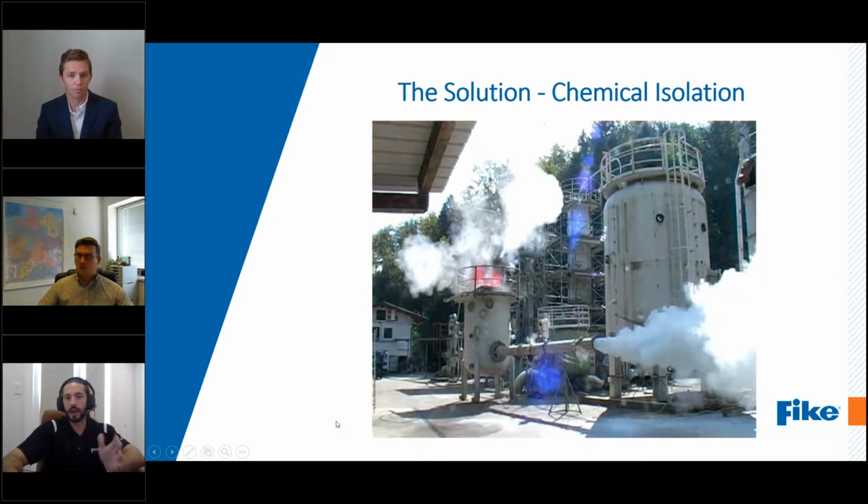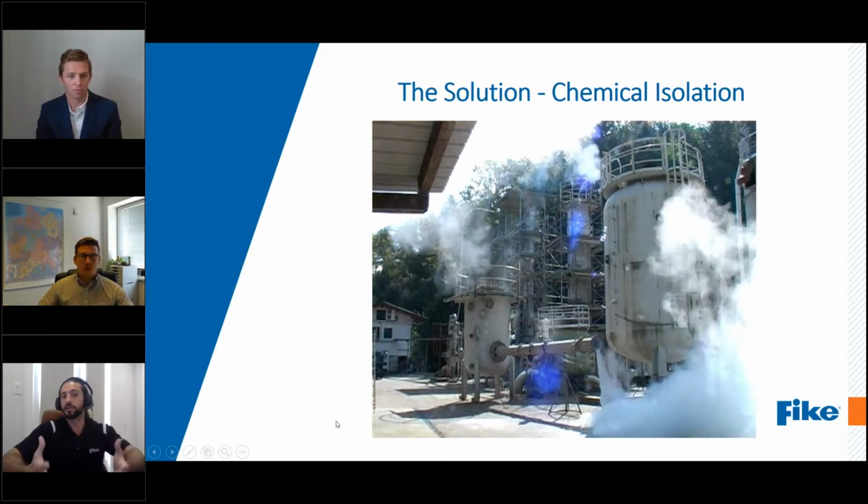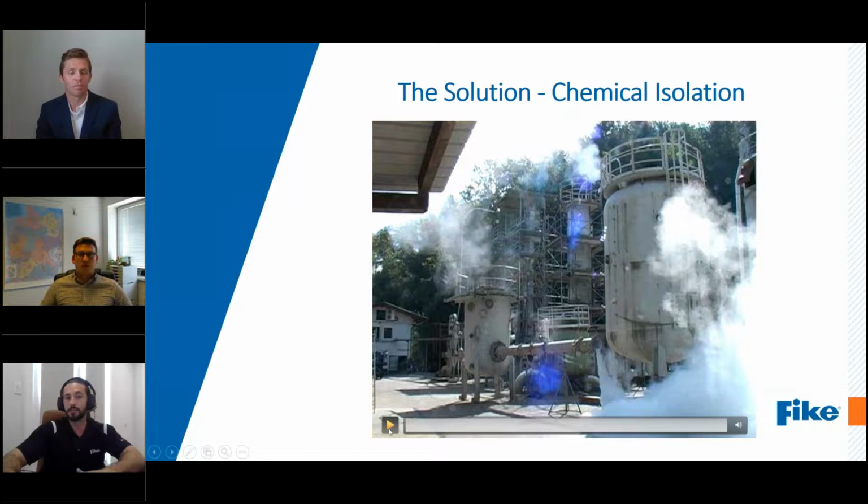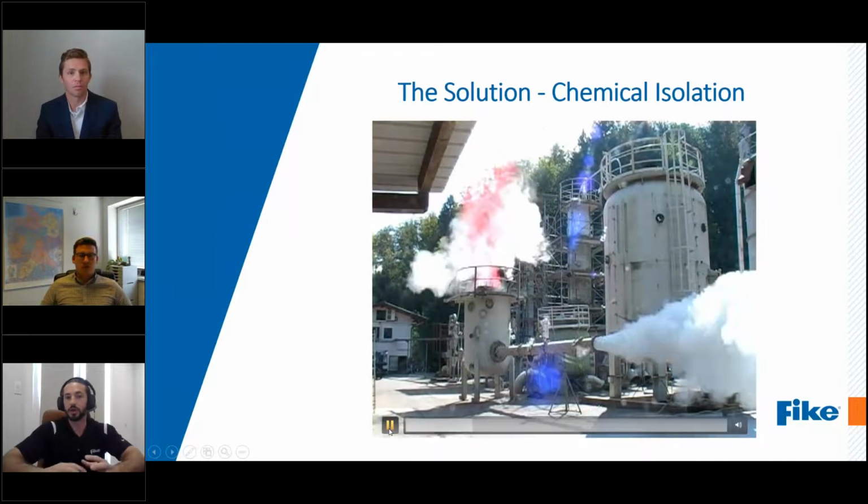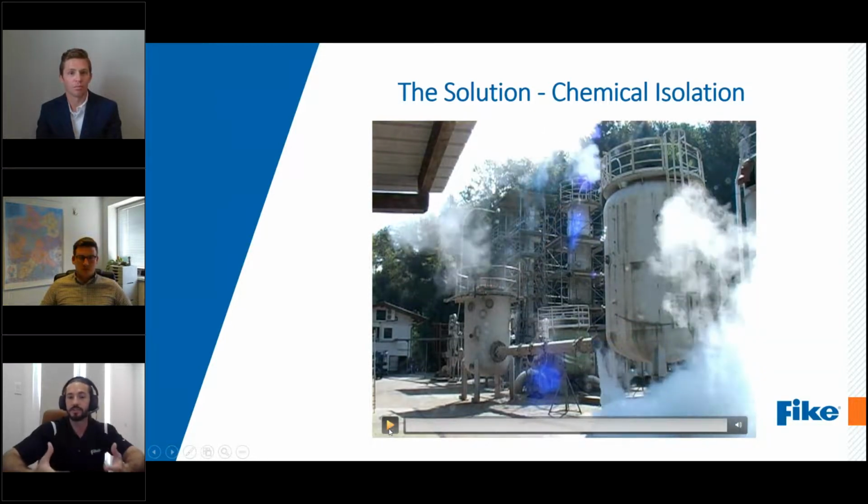So you see out the top, you have flame front being relieved through relief venting, a passive device like Carson showed you before. On that ductwork that you see there in the center of the video, you do have an SRD chemical isolation container, and you notice that there is no flame escaping out the open end of that pipe. All you see is a large quantity of inert material, our agent, sodium bicarbonate.